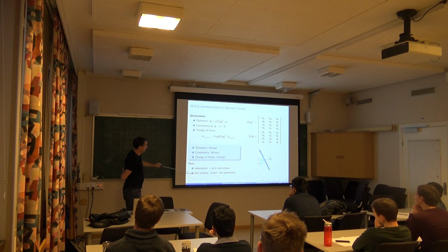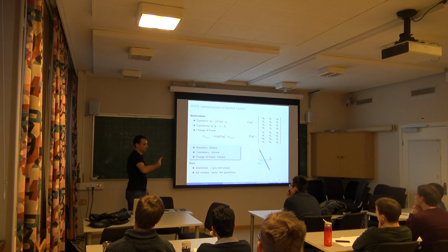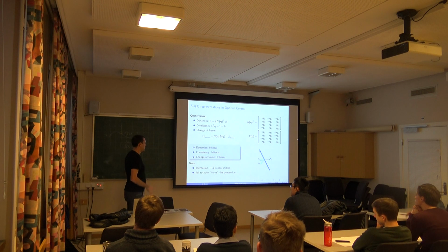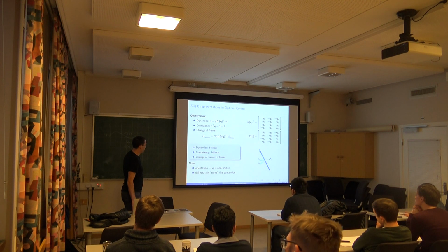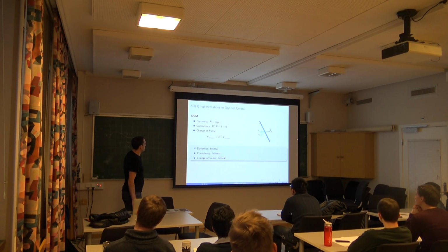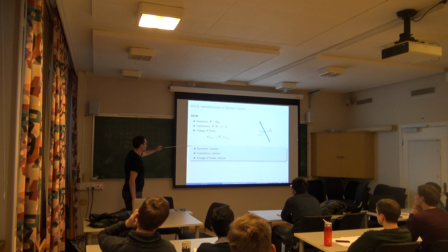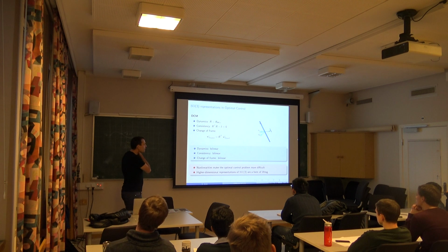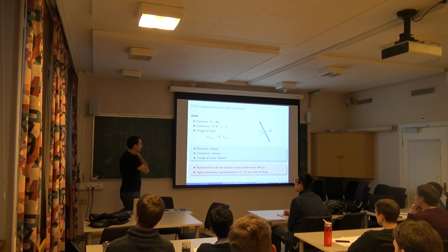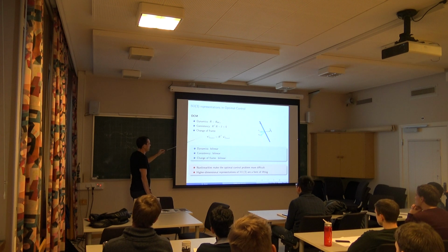Yeah, also in optimal control, you have to deal with that. If you make a full rotation, then your quaternion will flip. And if you impose some conditions on your orientations, you maybe get awfully lost from that effect. And the so-called direction cosine matrix, or using R directly, everything is bilinear in the dynamics, in the consistency condition and changes of frame. So it's pretty handy. Yeah, so that's, I'm not sure which is better between rotation matrix and the quaternions, but that's what we tend to use at least.